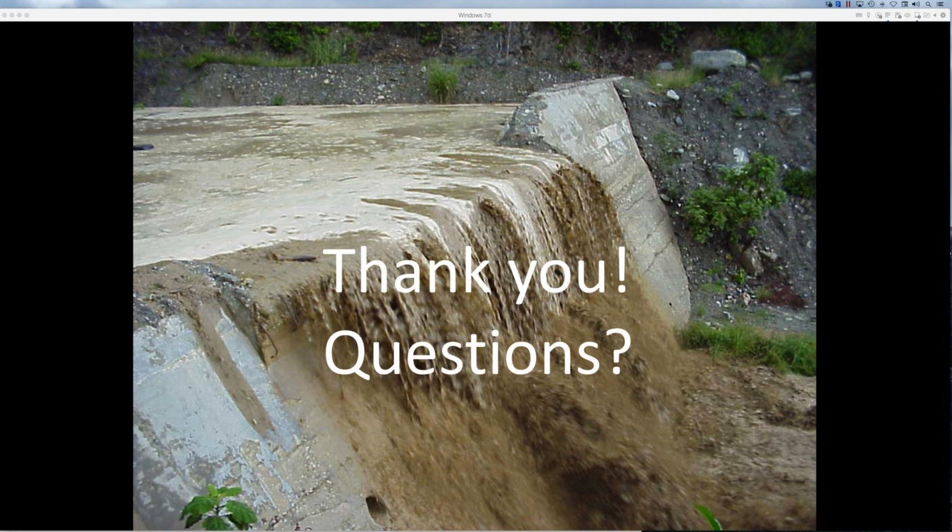I have a question here. Is there an option to apply sediment transport computation after water condition reaches a steady state? Yes, you can do a water-only simulation. It reaches a steady state, and then you use a hot start.